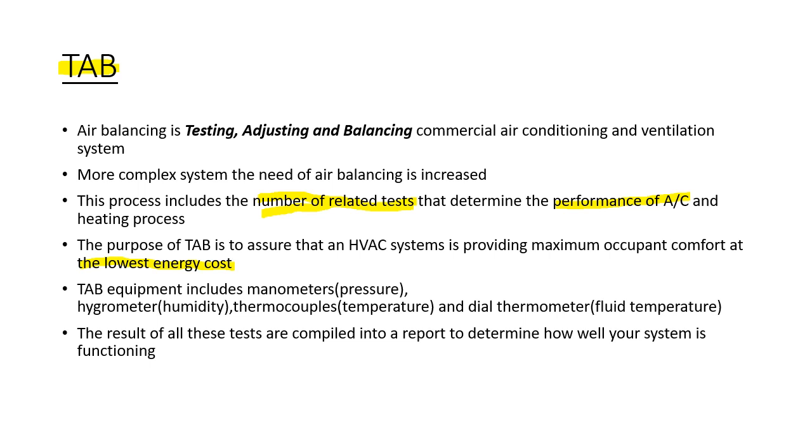So this test will involve several pieces of equipment, including manometers to measure the pressure, hygrometer to measure the humidity, thermocouples to measure the temperature, and also the dial thermometer to measure the fluid temperature.